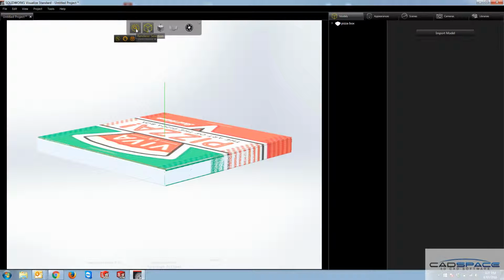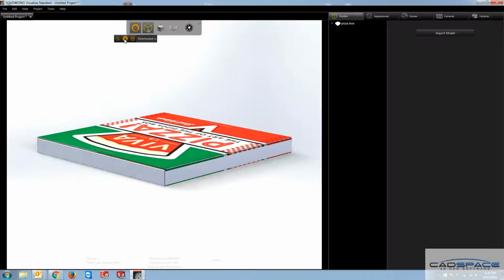By taking a look at these different modes that we've got for Visualize, we've got 3 modes of rendering. The first one is the preview render, which is a real-time presentation of our model. It's a high-performance, noise-free interactive rendering. The next one would be the fast rendering. If I click on fast rendering, you can see that it's visually accurate ray tracing with the fastest time to quality rendering. It's really good for hard objects without any complex transparency, and it's faster. It takes a bit longer than the preview mode.